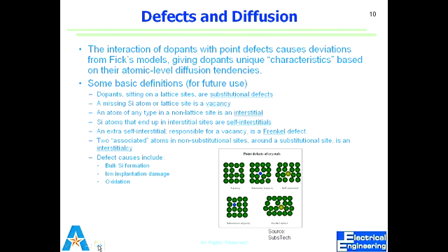In terms of silicon and semiconductor materials, you have to think in terms of crystalline structure, and there are these atoms which are rigidly spaced at specified positions. So anything that needs to pass through has to strike them, right? So collisions are what cause the degradation of mobility, or defects which may suck those charges in.